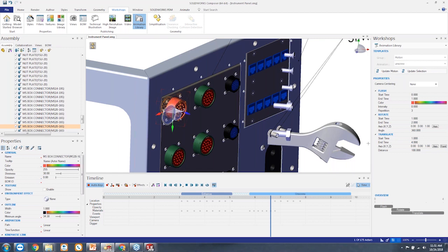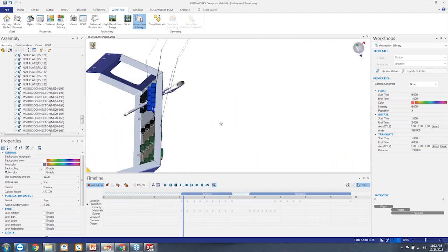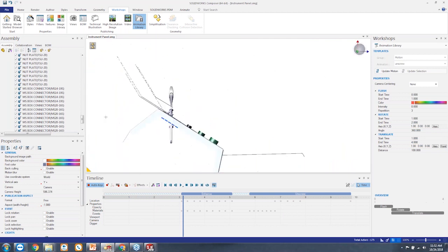So now instead of the Z axis, let's do X here, like that, and we'll change this to 0. That's for the translate, and then the rotate axis is going to be on the X as well. Let's try that. I'll set that to 0. All right, now I'm going to update. Now I'm going to play it back and see what it does. It lights up, rotates. Ooh, yeah, there we go. It is better. My axis is a little bit off, but oh, I know why. It's because this model isn't modeled directly on the axis. The model itself is at an angle, so that's what's happening there.